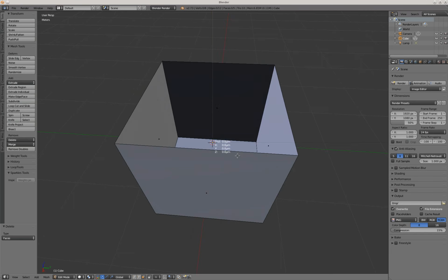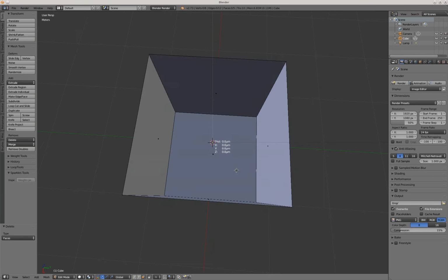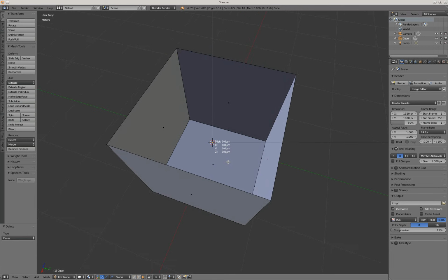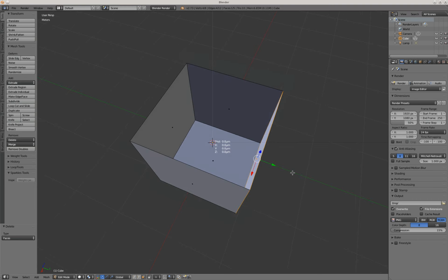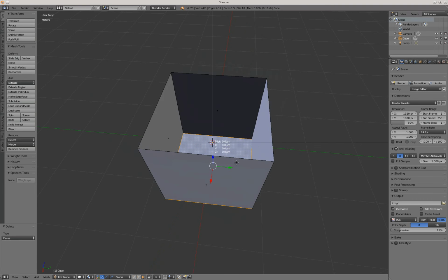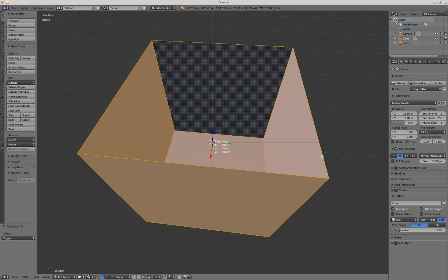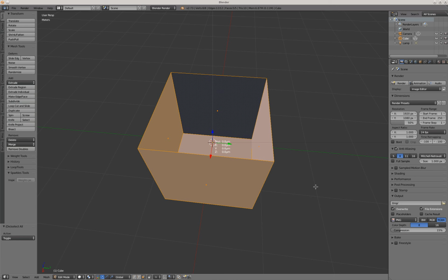But with the top deleted, we no longer have dimensions of length, width, and height of these side pieces here, right? Or bottom, for that matter. Any of these only have two dimensions, depending on which one it is. So if we wanted to make this box on a 3D printer, what we have to do is give it an additional dimension. So what I've done is select all the faces.